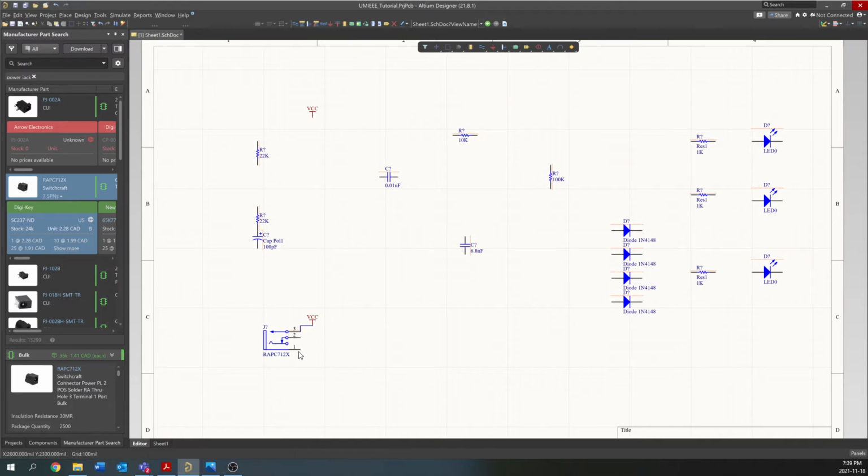These two pins on the bottom here, pins 2 and 1 on the jack, should both be set to ground. So we're going to ground that, and then we're also going to introduce wires and drawing wires. Wires are drawn by using the two little squiggly blue lines here in parallel at the top, and we're just going to connect those 2 points, and then that's connected. That's set up. So now that's our power jack.